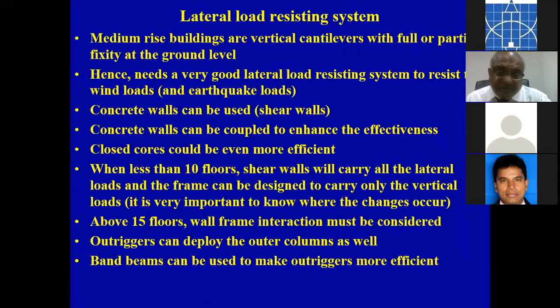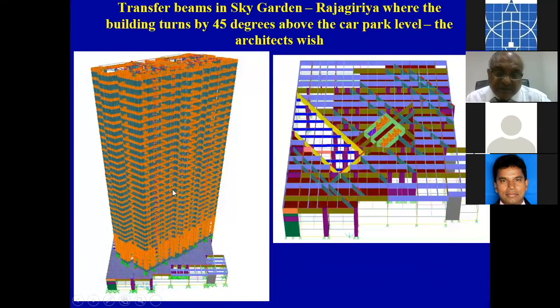And it looks like one building, like this. But when you consider the construction of the building, construction did not happen this way. Construction happened floor by floor. So what happens is this transfer plate will have higher bending moments and higher deflections because you are doing the construction stage by stage. And the bending moment due to dead loads can be as high as 30% of the original bending moments. So the bending moment will not be 100, it will be 130 or 135. Shear forces increase by about 10% when you are doing stage construction. And modern software has the capacity to do this analysis, although it takes a little time.